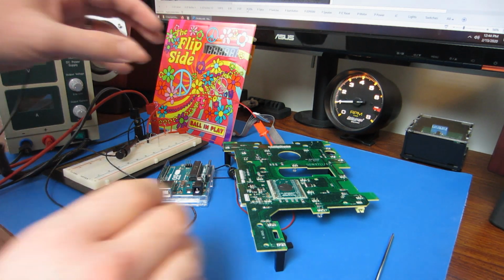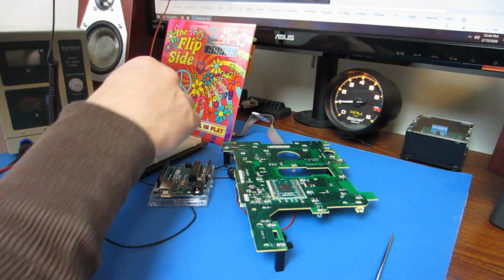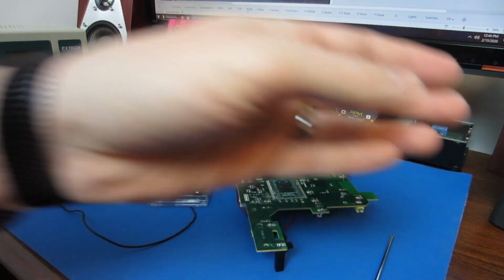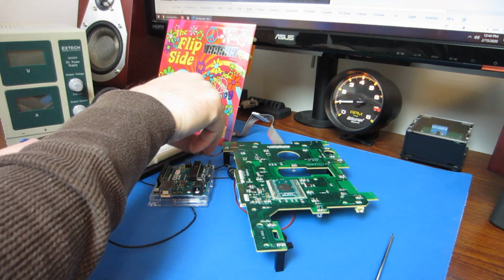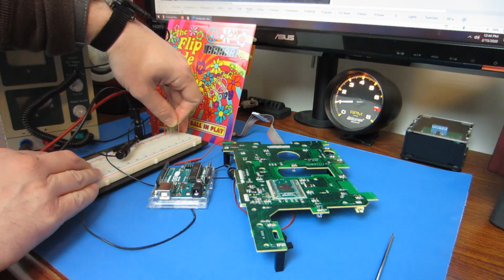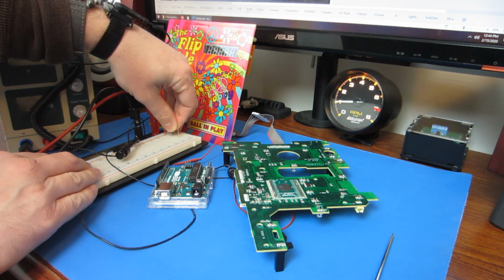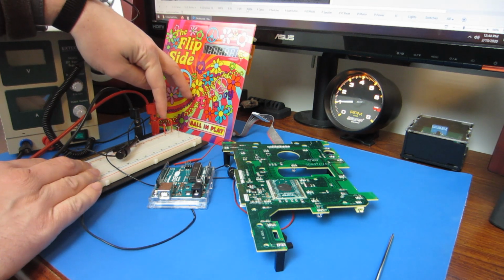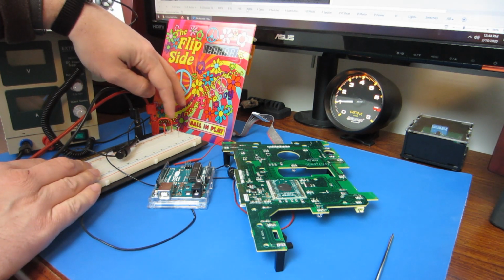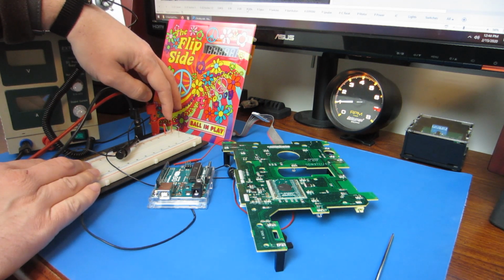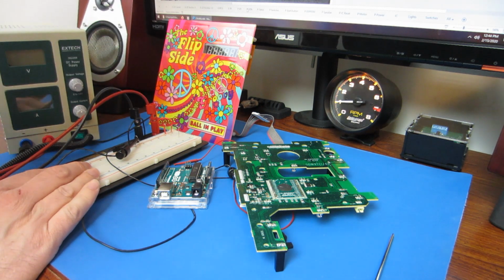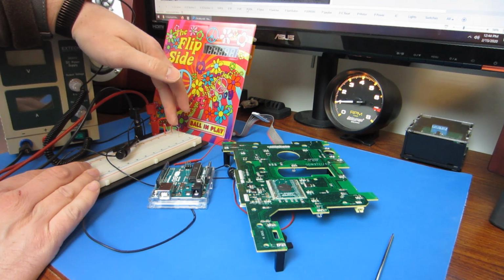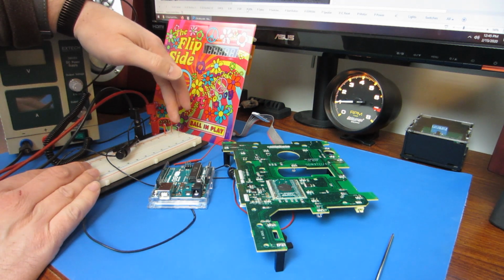Let's pull this off, I'm done with that. I was using that diode as just a convenient place to hook my logic probe, but if I were to string this diode off of my positive battery voltage, which I'm sending 4.7 here now, I could set this at 5 and count on the voltage drop of this diode to lower it by about 0.6 volts, I think.